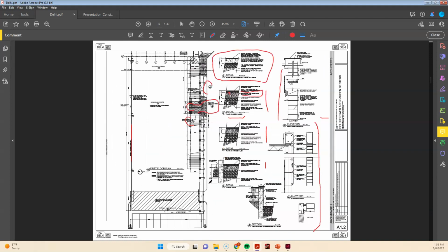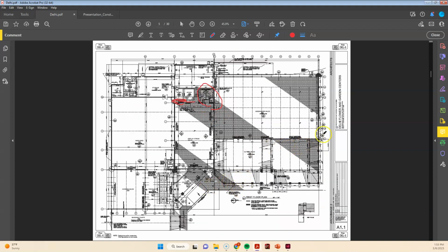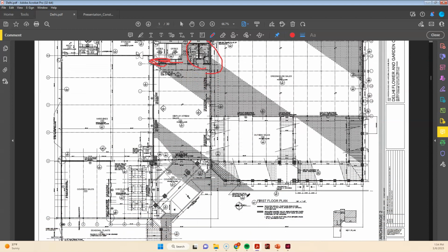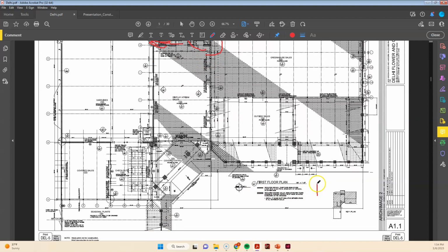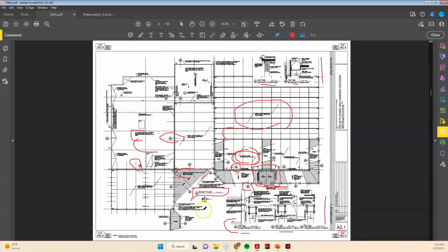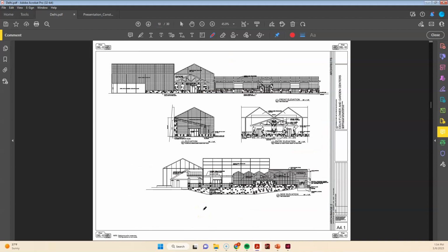So just let me circle back. I promise I'm moving on. The elevations, as I look around this floor plan, I don't see elevation tags really. Typically I would expect to see elevation tags out here with arrows pointing to the elevations, but I don't see them. I don't see any here, so we might be left to kind of piece this together ourselves, which by this point should not really be a problem, right? Because we've kind of walked through it.